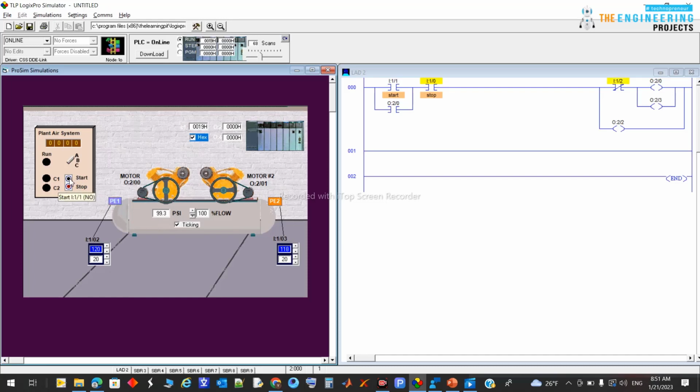Okay, so now you can see this value, because it is less than 120. So by getting further down from 120, this one is ready to start the process again like this. So the compressor is running again, okay, to increase the value by having the flow valve reduced, so the pressure is getting up.